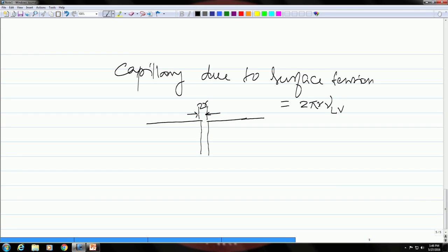Now, you can apply the liquid through the top like this, and if the solid surface is wetted by the liquid, then due to this opening and the capillary force which develops, this liquid will go inside the crack, in this fashion.